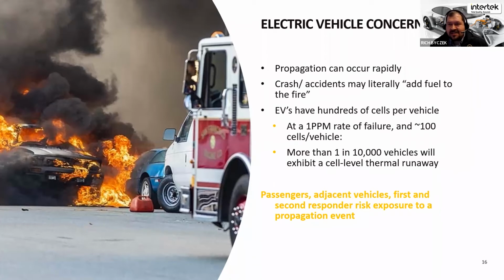You've got hot exhaust systems. You've got a good mix of conditions that can trigger a fire, especially when there's a crash event between vehicles. And that fire alone could be enough of a stress source to trigger the battery or cells within the battery to go into thermal runaway.